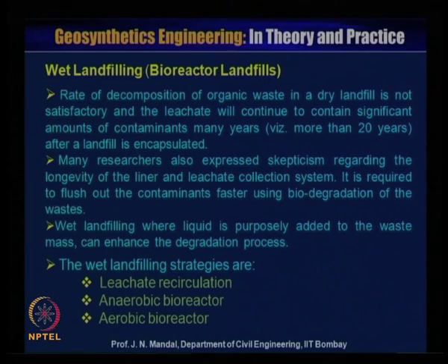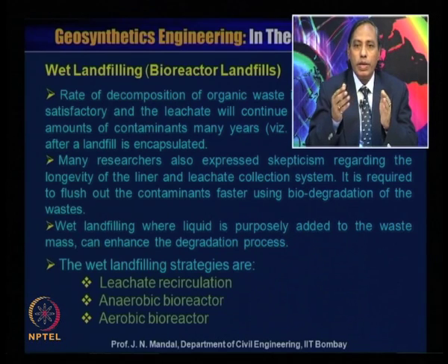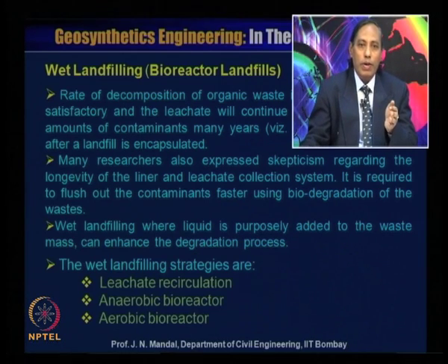So wet landfilling, that is, the bioreactor landfill. The rate of decomposition of organic waste in a dry landfill is not satisfactory, and the leachate will continue to contain a significant amount of contaminant for many years, more than 20 years after the landfill is encapsulated. Many researchers also express skepticism regarding the longevity of the liner and leachate collection system. It is required to flush out the contaminant faster using biodegradation of the waste. Wet landfilling, where liquid is purposely added to the waste mass, can enhance the degradation process. The wet landfill strategies are leachate recirculation, anaerobic bioreactor, and aerobic bioreactor.